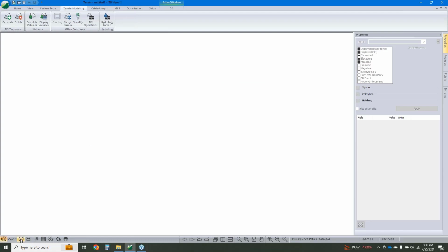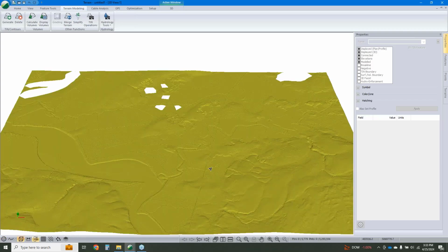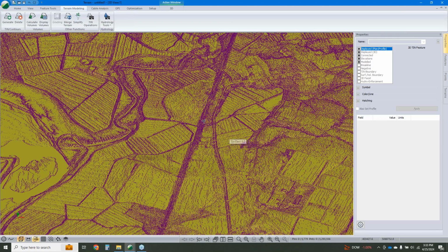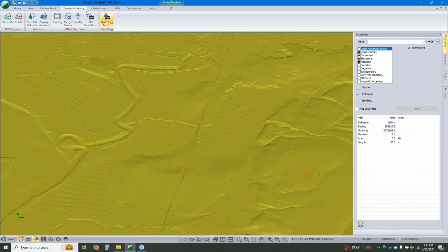We'll click our little 3D view here. So I'm a sucker for the 3D view. So we can see we've got, well, pretty good representation of the ground still. And if I hit Control A, just so we can see all those points that aren't being displayed, well, we've got pretty dense data on those irregular slopes, but in the fields and elsewhere where we don't need that extra data to really visualize and model what's going on, we've got much sparser. So that's the simplify tool, the feature simplify tool used on DEM data. And we'll send it back to Erin.